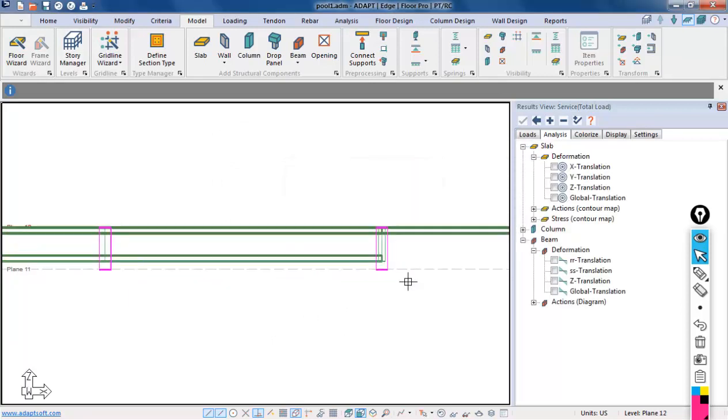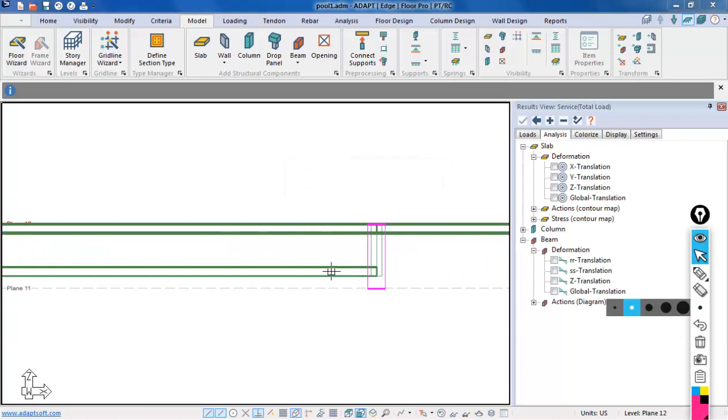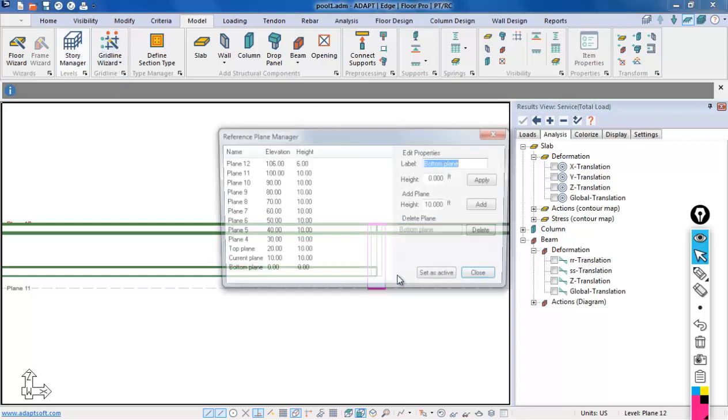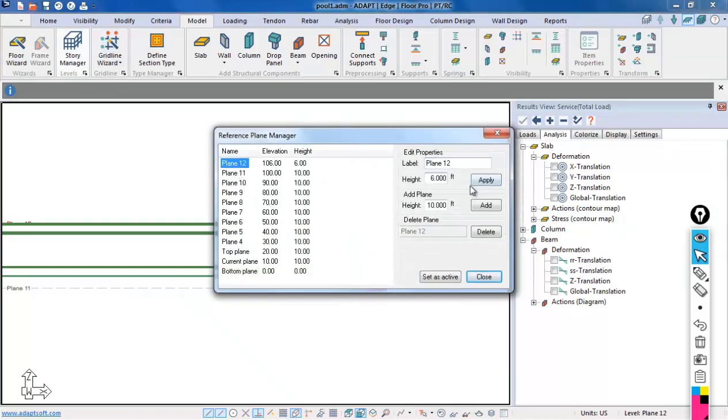Okay, now we have a condition where the beam and the column centroids may be in a position such that the beam midpoint is above the column midpoint, if you will. And here we may have to shorten that just a little bit more. We're actually going to shorten it down to 58 inches. So 4.83 feet is what we'll use in this case. We'll make that such that it's the same as the...